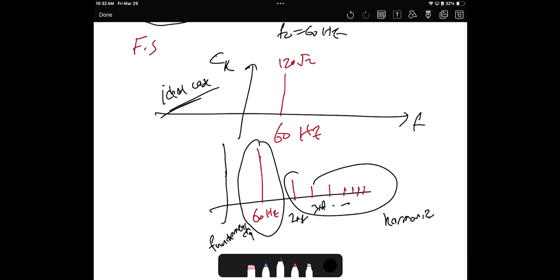How to solve it? Because sometimes electronics cause the problem, I can solve it by using other electronics, by creating something we call active filters, which is basically based on op-amps and different parts. Or you can use passive filters using LCL filters, or L filter, or LC filter, whatever. So there are several types for it. But sometimes the problem is because of electronics, and the solution comes from electronics as well.